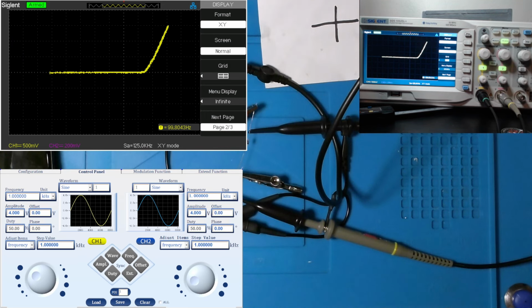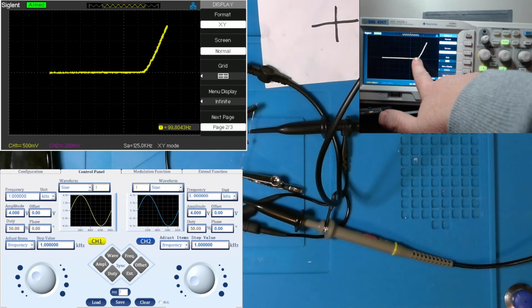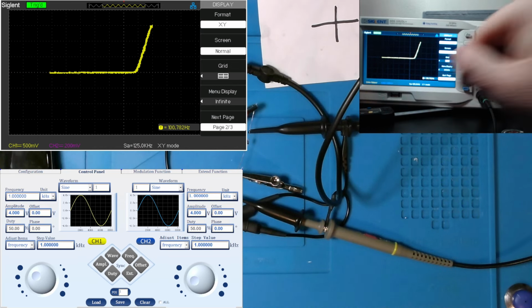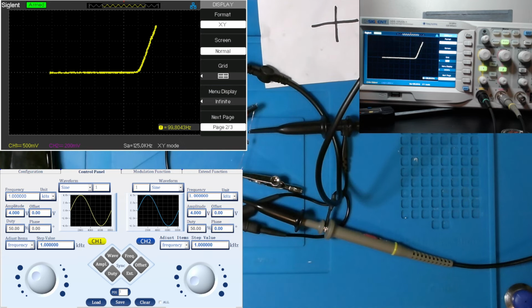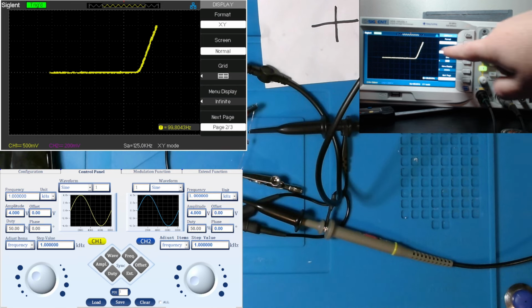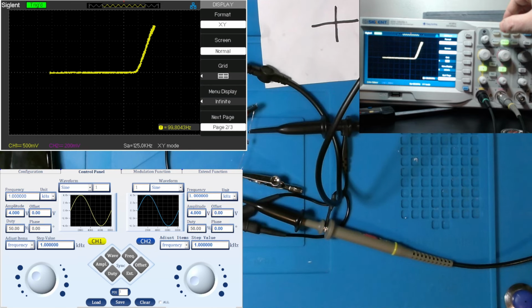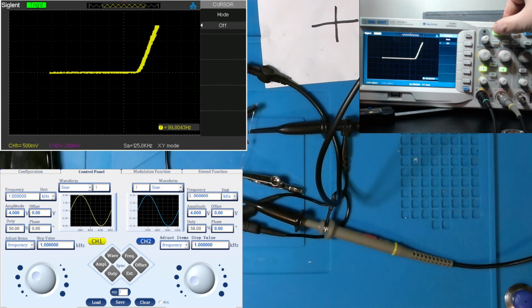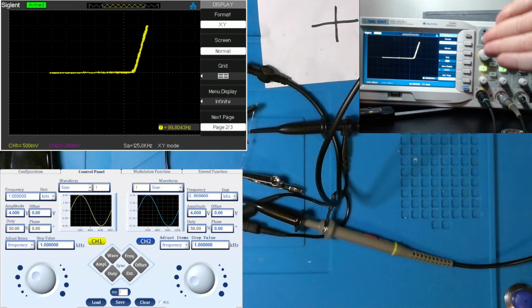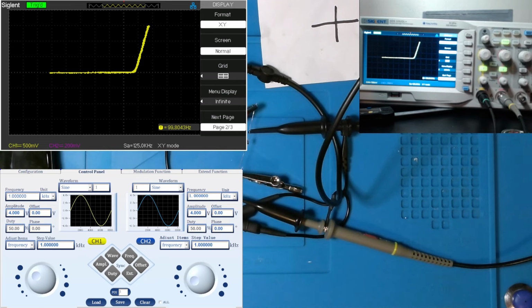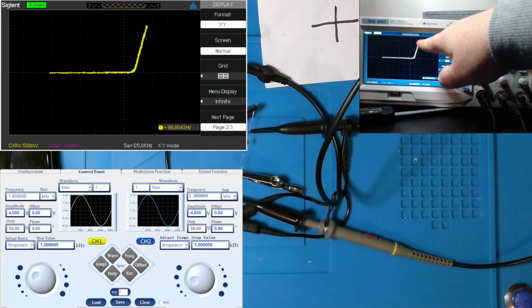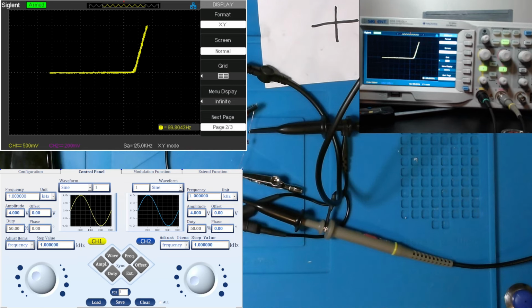And here's what our diode looks like. And we can see the forward bias voltage right here. That's because I'm bumping my probes. So if I keep my hands off them, we can see our forward voltage here. Unfortunately, my oscilloscope does not allow me to turn on my cursors when making this type of measurement, but you could measure the forward voltage of your diode and check it. But traditionally, your diodes are going to look like this.